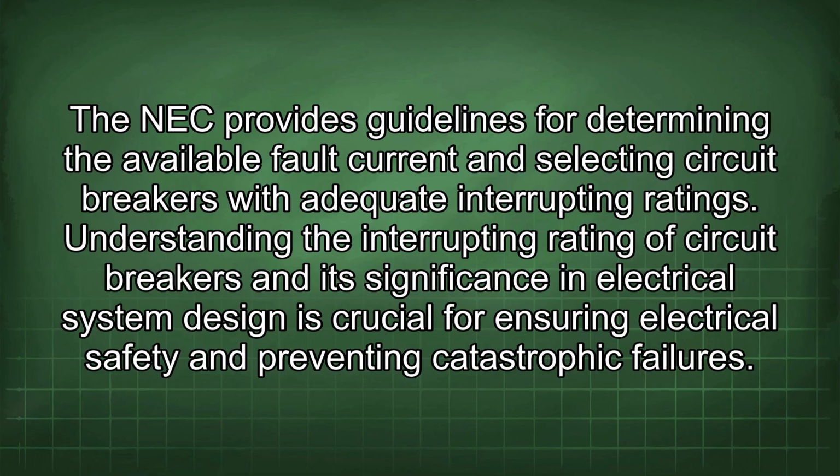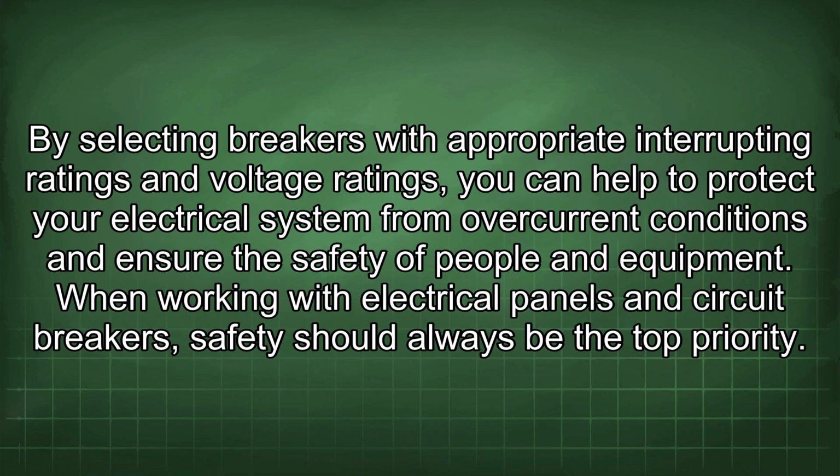Understanding the interrupting rating of circuit breakers and its significance in electrical system design is crucial for ensuring electrical safety and preventing catastrophic failures. By selecting breakers with appropriate interrupting ratings and voltage ratings, you can help to protect your electrical system from overcurrent conditions and ensure the safety of people and equipment.